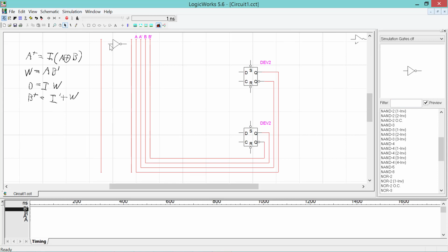And this will allow us to develop I prime from I. So here is I and I prime. Because we have I prime for B plus, we have to have the inverter. For A prime and B prime, those are developed automatically from the flip-flops that hold bits A and B for the current state. So we don't need extra inverters for those two bits.